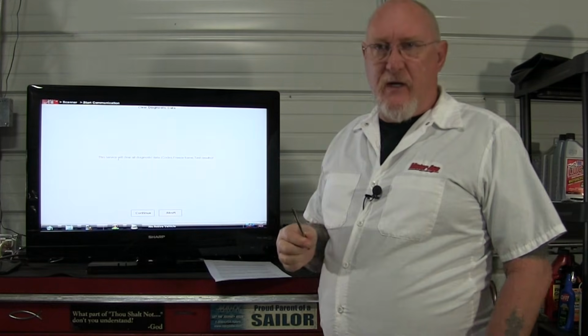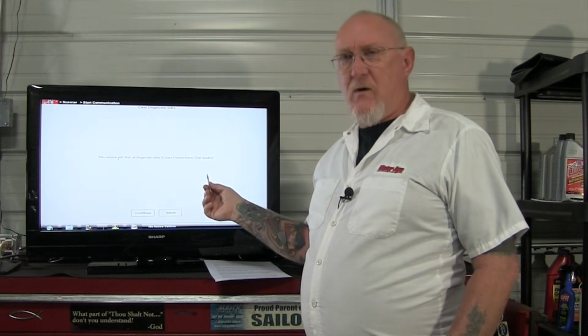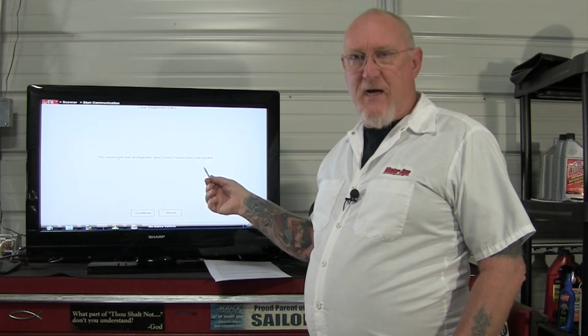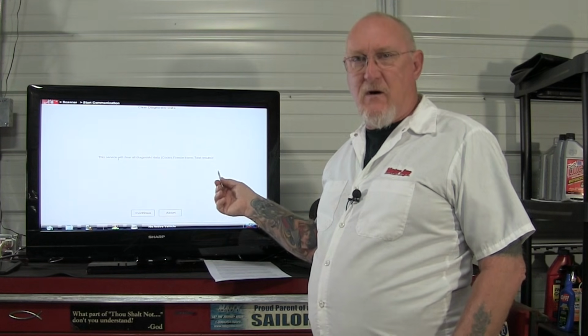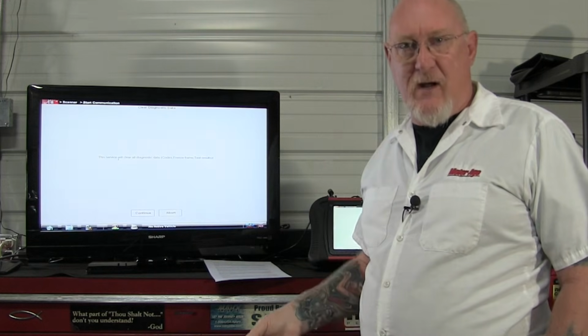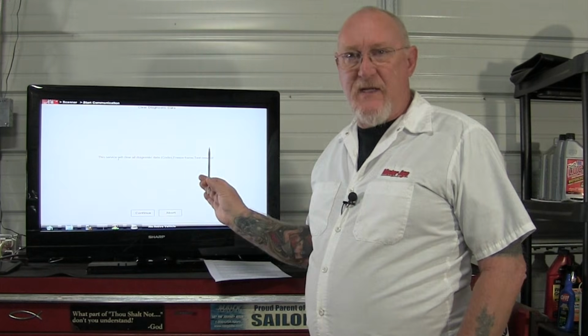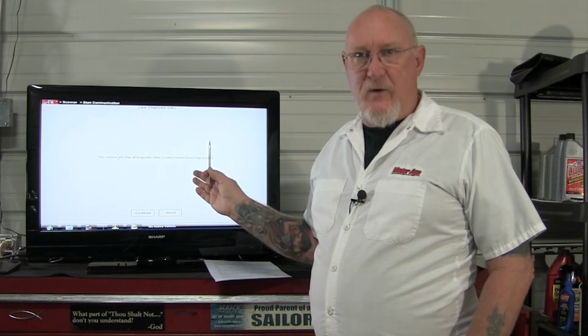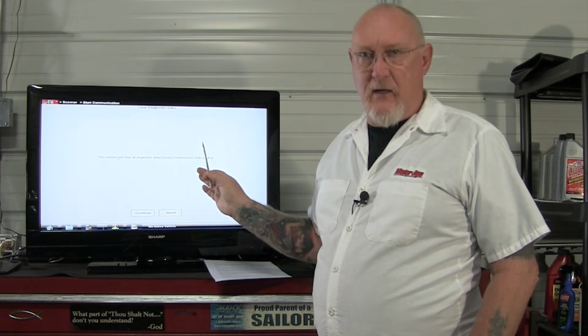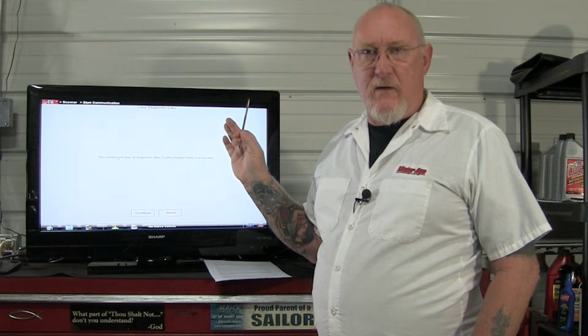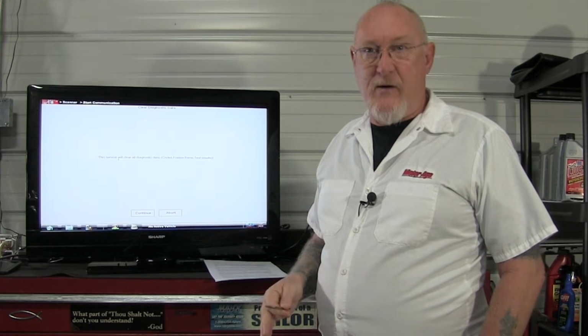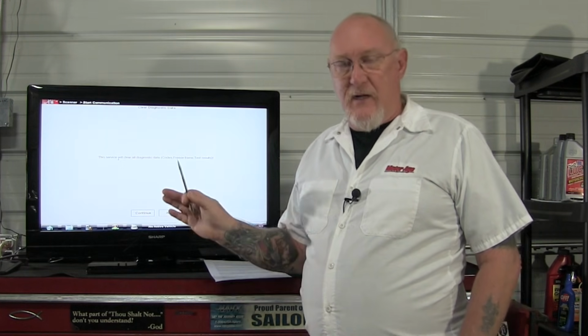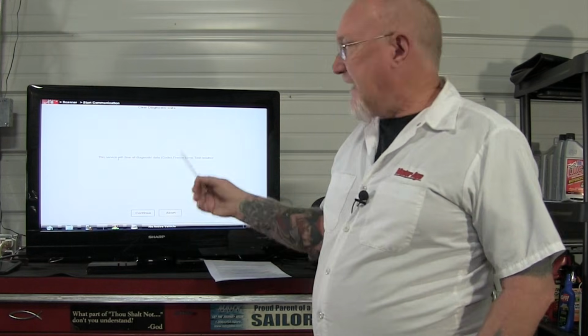Like my buddy G. Trulli likes to say, if you clear your codes before you've accessed all the possible information you might need to fix the car, it's like pouring bleach on a crime scene. You're going to wipe all the evidence out, and then it's too late. You'll never retrieve it again. So don't clear anything until you're ready to take that test drive and verify the repair that you made. Until then, leave it alone. That way you'll always have access to it.